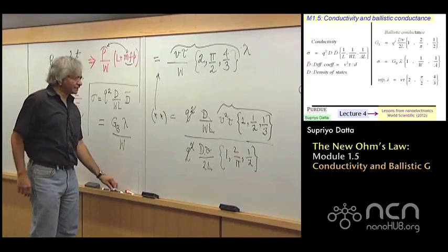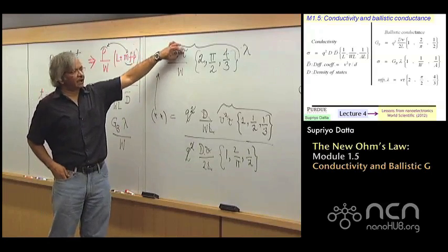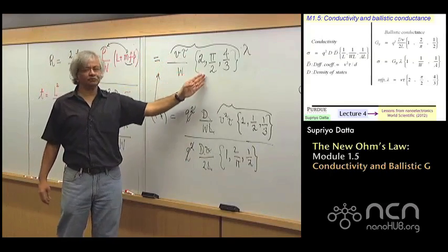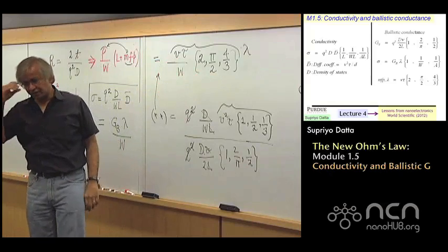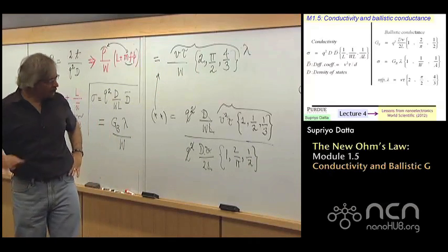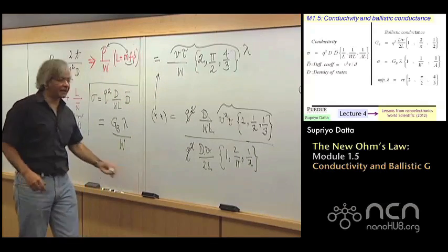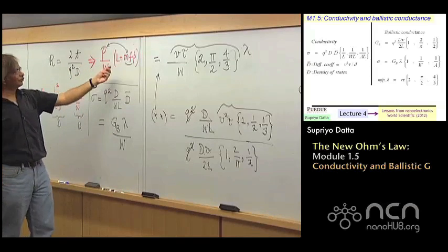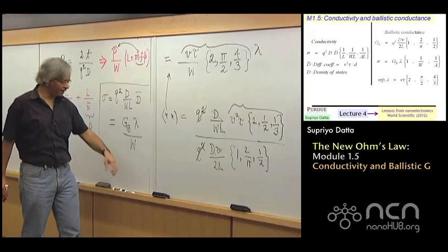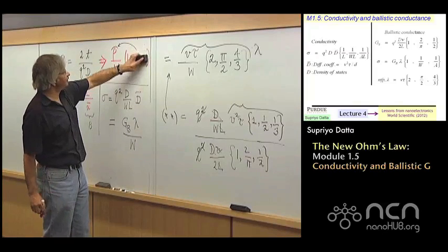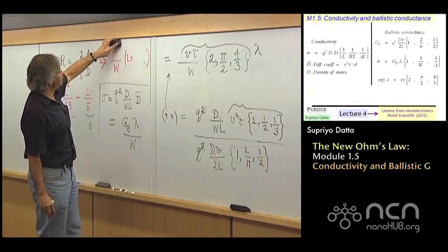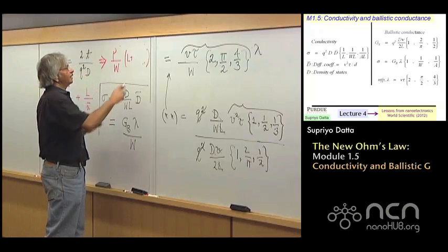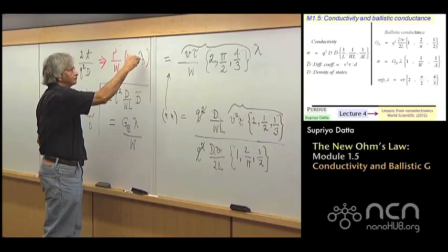Now one thing you might say is, why didn't we just call V tau the mean free path? Why include this strange factor, which again is different in different dimensions? Well, you could do that, but then the modified Ohm's law, instead of looking like L plus mean free path, the way you have now defined it, the way Ohm's law gets modified is that to this L, you add a lambda, the mean free path.